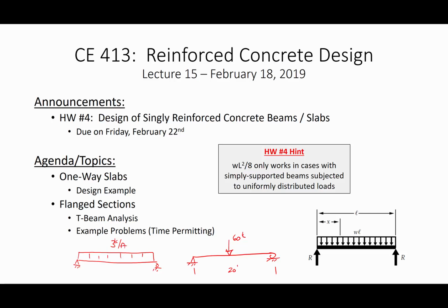And we'll use WL squared over 8. And if you do that, I'm going to say, do me a favor, take the hand like that. No. This WL squared over 8 only works if this is your loading, okay? It only works if that's your loading. So if you have this loading scenario, it doesn't work at all.